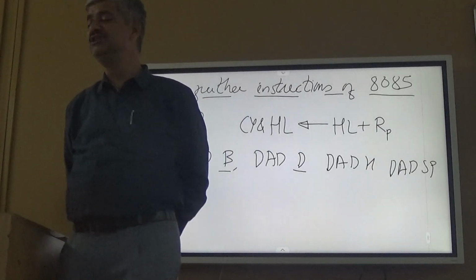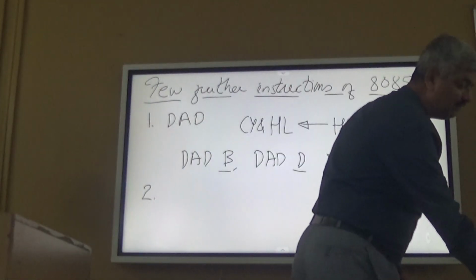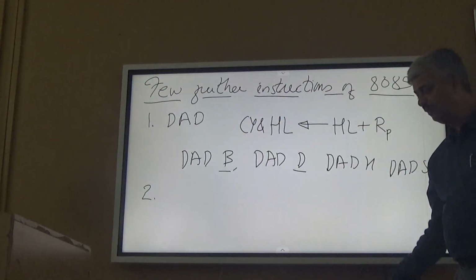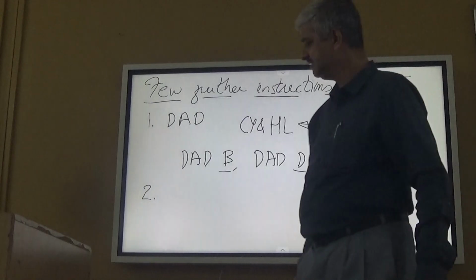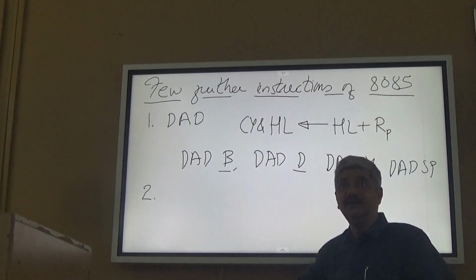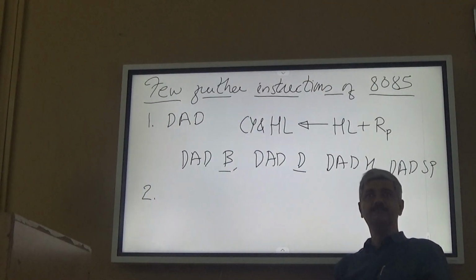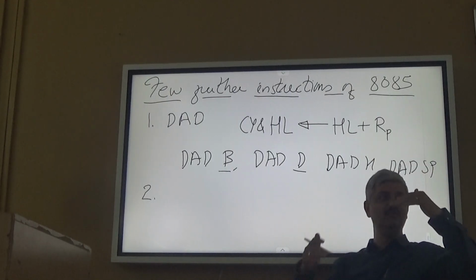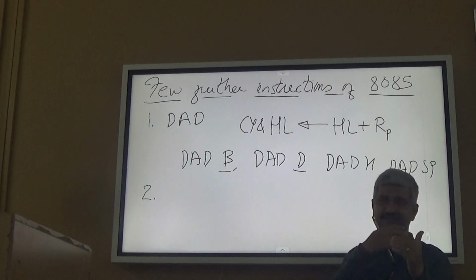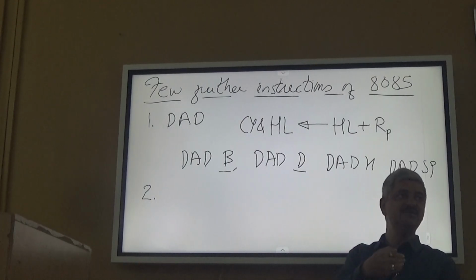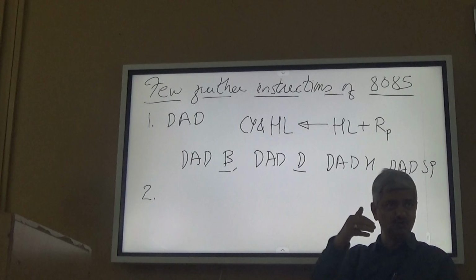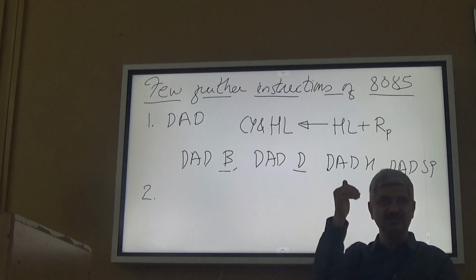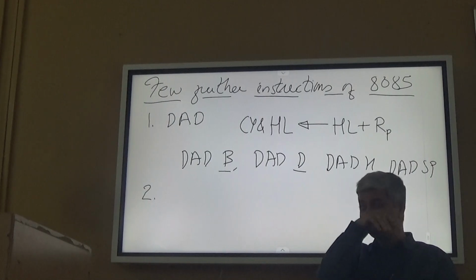When we want to initialize some registers, we use instructions like MVI. In the instruction set, under data transfer, when we want to initialize, we use immediate addressing mode. So MVI A, MVI B, like that there are 8 move immediate instructions.